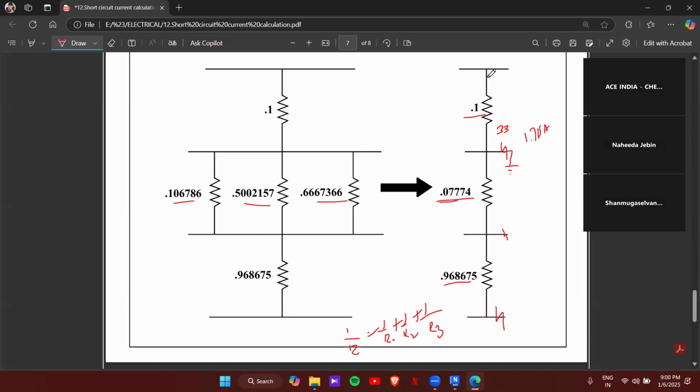If a short circuit occurs here at fault 1, 1.75 kiloampere will come at fault 1. But if the earthing fails at fault 1, the short circuit current will come to fault 2 also. The same short circuit current will come to our fault 2 side also. So the earthing at fault 2 should have the capacity to earth fault 1 plus fault 2, combinedly.